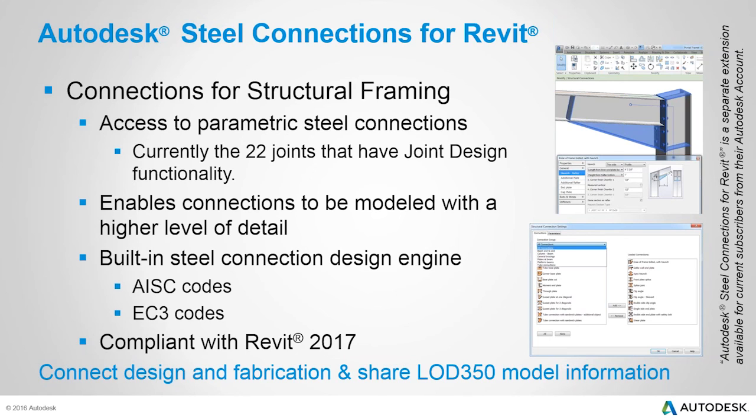But what can happen, your engineers, if they're using Revit, or the architects, whoever's using Revit, can go to that level and they can look at that and they could play with a haunch joint, experiment with parameters and bolt spacings and so on, get it right, get it to pass EC3, and then send that model to you. They haven't got to give you scrappy drawings of each joint in each position. They can have the model which has the proper approved dimensions and joint on there. You import that model into Advance Steel and you will have a fully functioning, fully editable haunch joint or whatever other type of joint in Advance Steel.